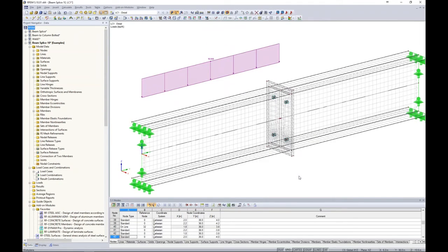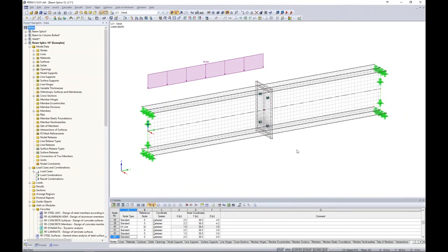Now there is an iterative process with this. You can continue decreasing your FE mesh size smaller and smaller, and sure, your results are only going to be more accurate. But at a certain point, you're going to be increasing your solution time to be very high in comparison to how much your results are actually changing. So you'll get a better feel for this as you begin to model in finite element software more and more.